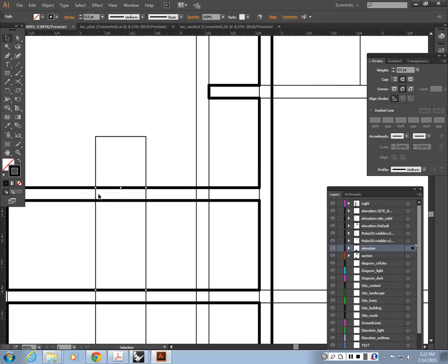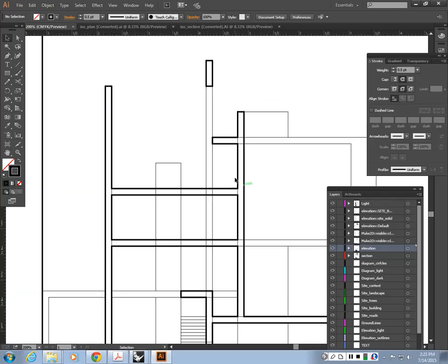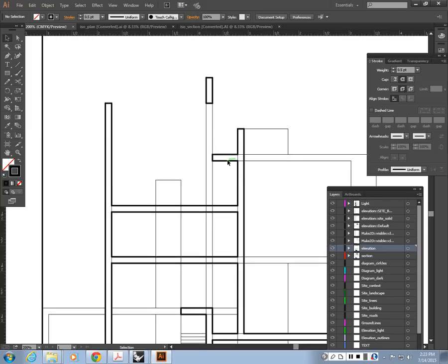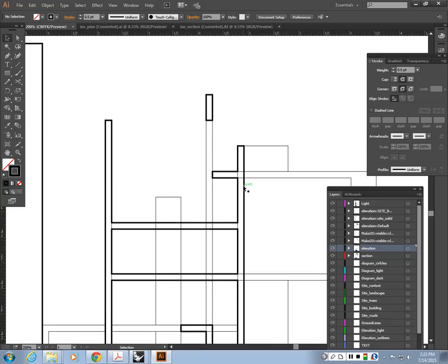Not over the wall that is cut. There shouldn't be anything inside these cut wall lines. This should be full white. No other lines. Well, if there's something above that goes through that wall, it will be disconnected when it goes through that wall in the line drawing. So it will be empty.